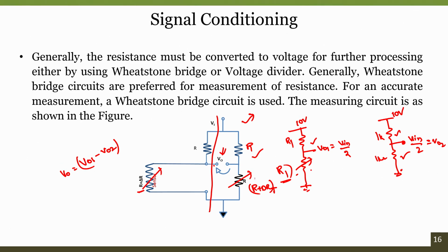Since both the sensor materials are of the same type, introducing another sensor into the second pair of the resistive divider network topology can compensate for the temperature effects. First-stage temperature effects can be completely compensated using this. This is another advantage of it.